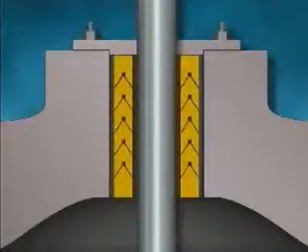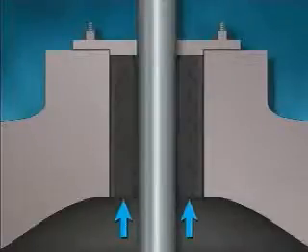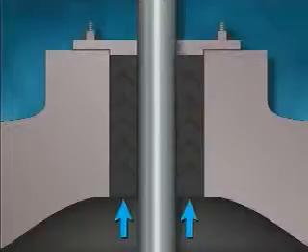When hydraulic packing rings are stacked in a stuffing box, they're arranged so that the open end of the V faces inward towards the bottom of the stuffing box. Internal fluid pressure moving up along the shaft forces the sides of the lower packing rings outward against the shaft and the wall of the stuffing box. Fluid pressure also forces each ring against the ring above, causing the rings to expand to fill the stuffing box. This internal fluid pressure actually forces the rings to seal. The gland follower simply holds the rings in place.